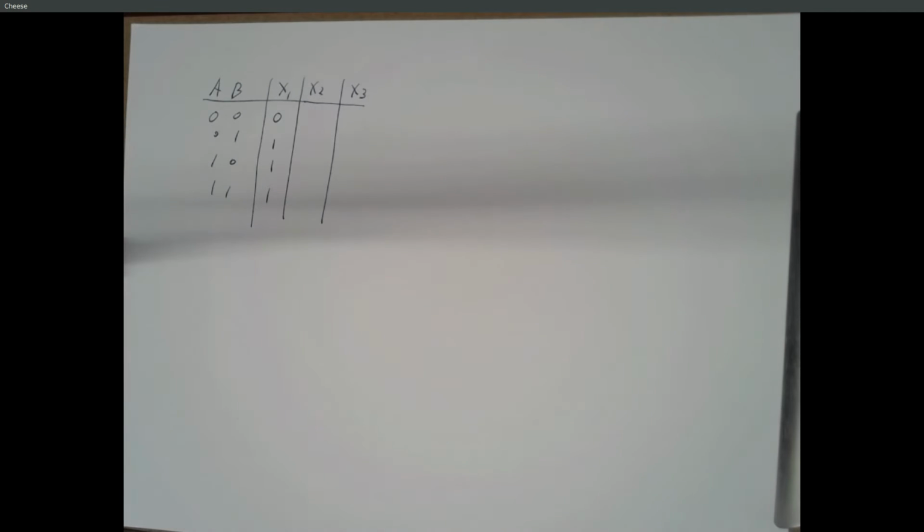For one, those unknown chips, sometimes it's hard to read the numbers on top and know which one is 1, which is 2, which is 3. So I think there was some switching around going on inadvertently. Secondly, connecting something to ground is not the same thing as leaving it disconnected.